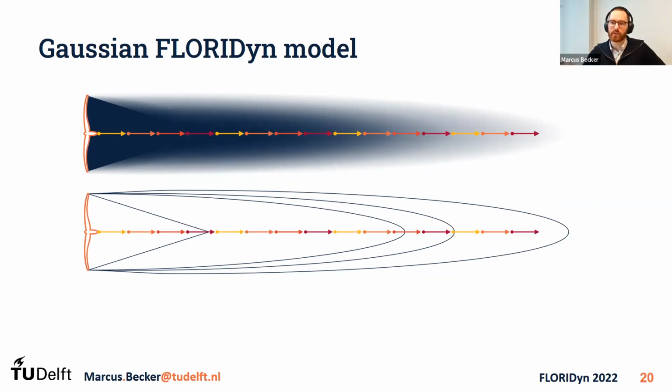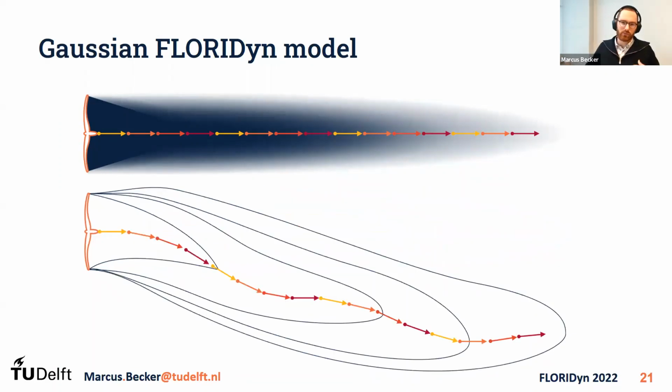So observation points still get created at the turbine and then travel downstream. And in steady state, we have the same behavior in the top where there's the wake coordinate system, and then in the bottom, which is the world coordinate system. But then if in the world coordinate system, we have different wind directions or changing wind directions, turbulences, then the observation points travel according to the wind directions. But in the wake coordinate system, they still only travel downstream.